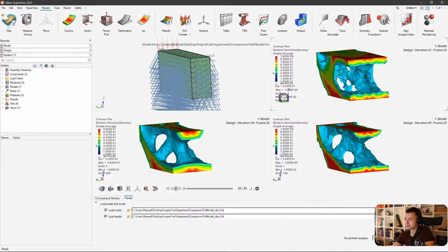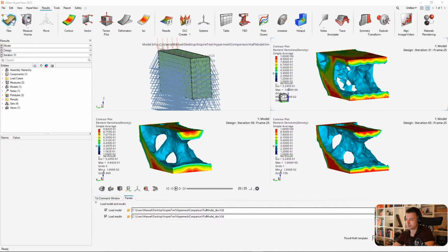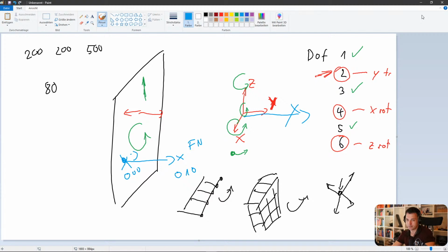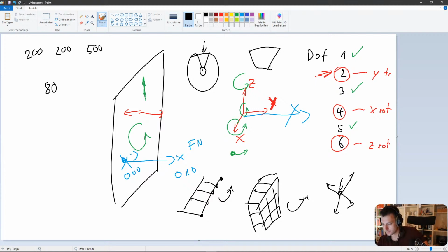And we did not even cover the things you can do with custom systems, because right now it's pretty easy, as our symmetry plane was correlating with one of the global axes. But what if that's not the case? What if you have something like a structure which is somewhat circular, and you just want to have a little section cut out? Those two boundary conditions you have then on this plane and also on this plane are not correlating with the origin coordinate system.